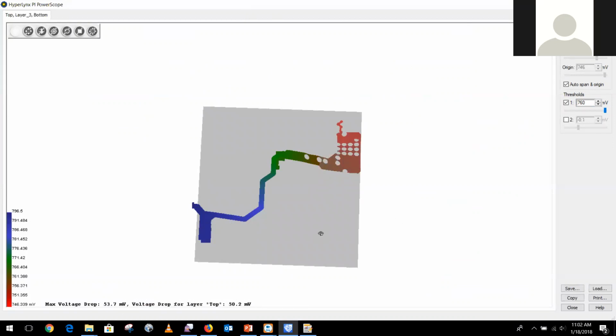You should have a bigger plane here and a narrow trace there. So you can quickly identify that, yes. Now let me go around and measure things. I can put on the cursor and I can say, okay, here's 0.794, and it's dropping down, and lower.